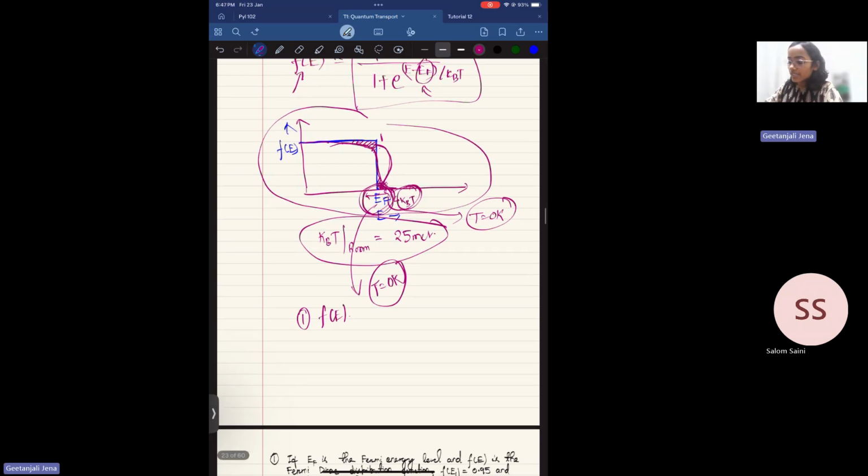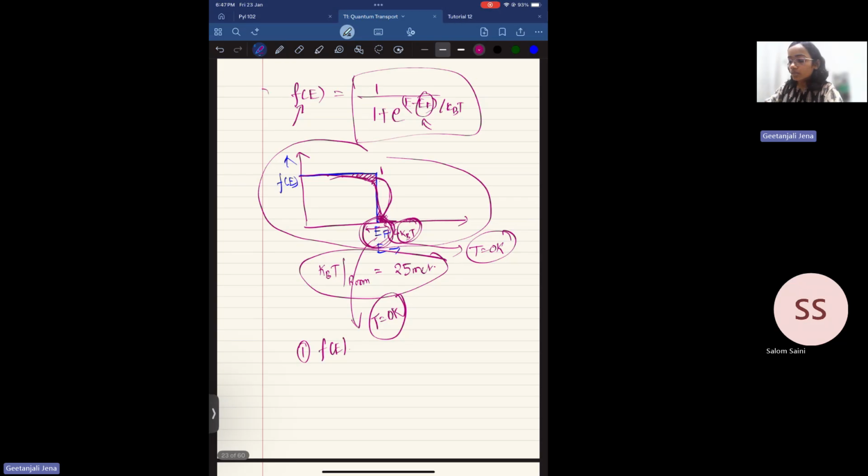And besides that, these are some of the lacking of Drude's model. It doesn't consider the density of state, it doesn't consider the Fermi-Dirac statistics, the probability of occupancy. Also, it completely ignores the effect of a channel interface. Sorry, the material interface, contact interface.